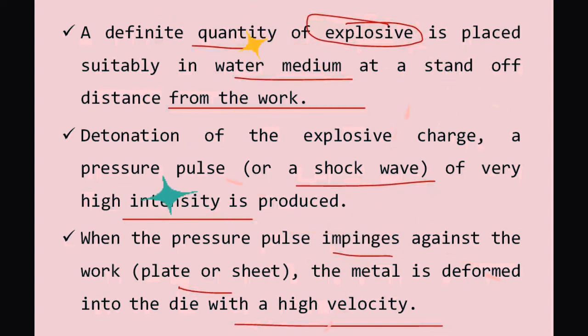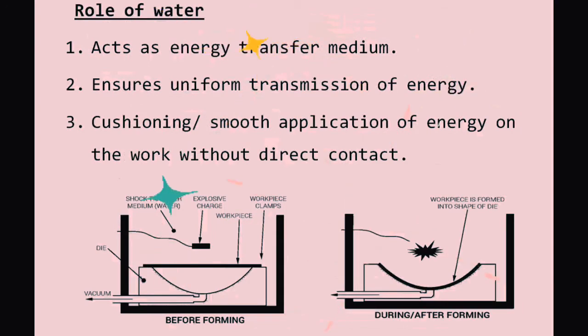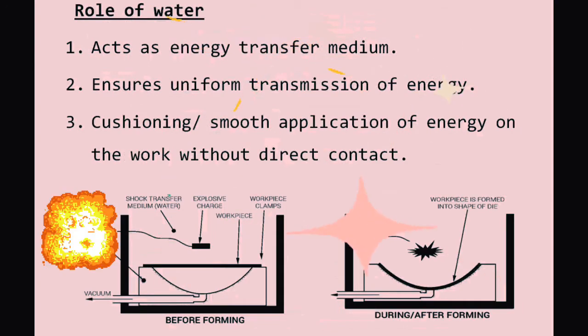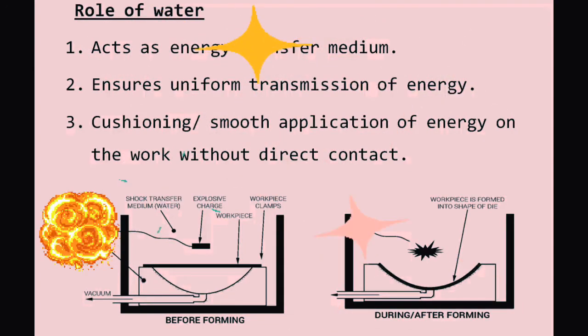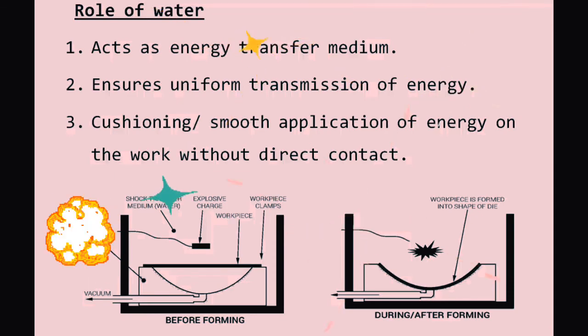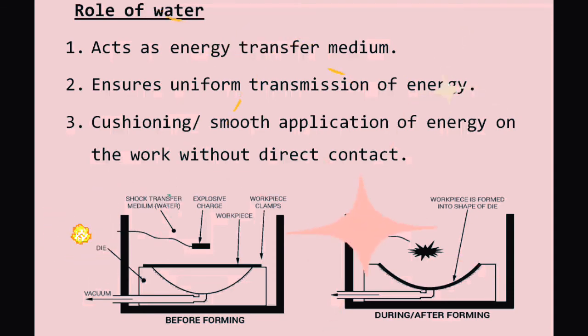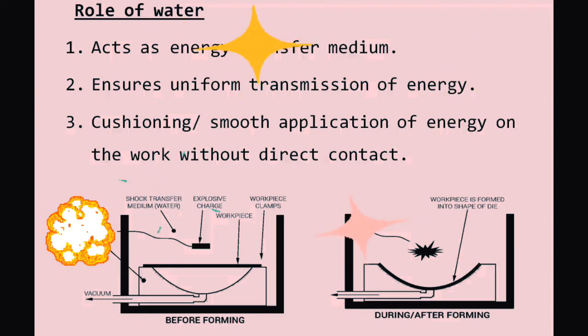So before measuring the stand-off distance, you have to choose how much explosive material is needed for that particular process. Everything has to be calculated before doing the process. Each and every explosive forming is conducted with the support of a medium, which is water.